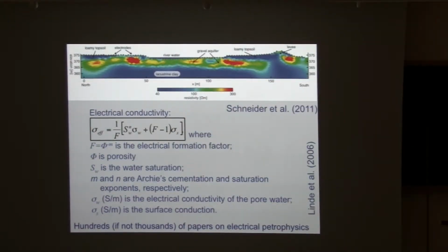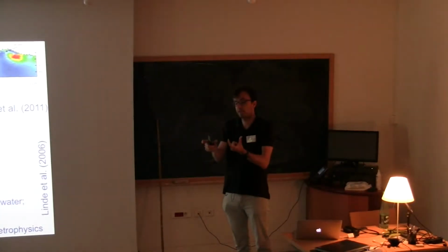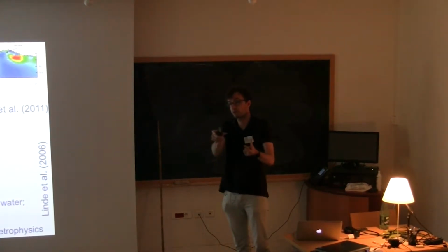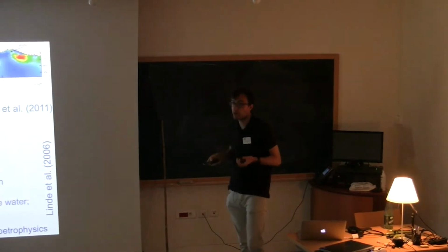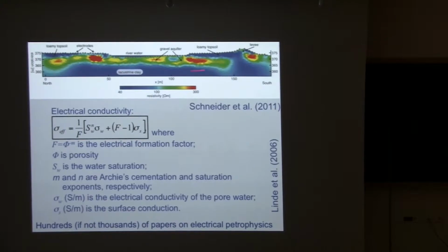ERT, electrical resistivity tomography or resistance tomography, is the basic thing. For electrodes, you increase the spacings and you move along. So you get measurements at different separations, at different horizontal locations, maybe in two horizontal directions. You increase the spacing and you see more in depth. And from inversion, you can obtain a model. We'll call it often a tomogram. Here's just a simple example.